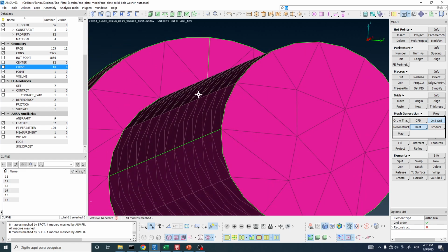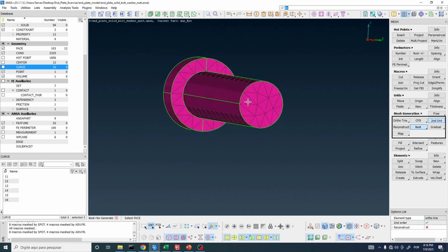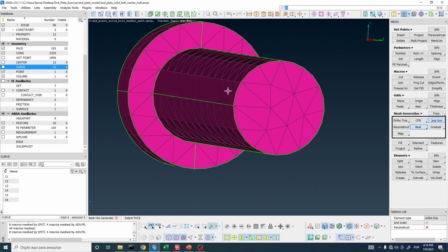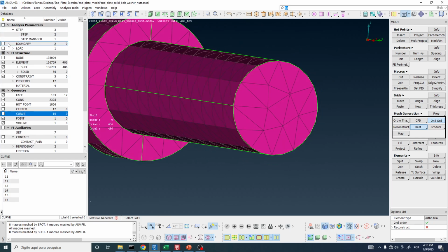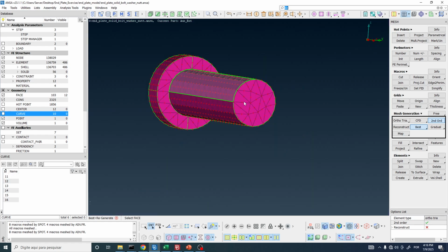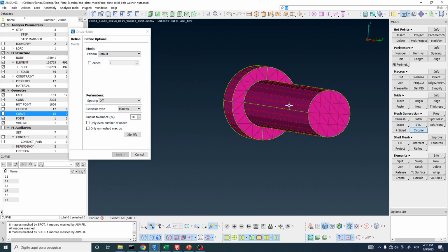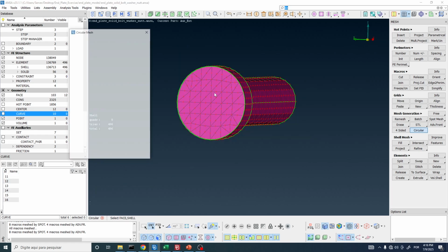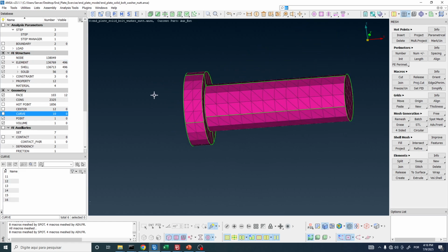And now if we zoom in, you see that we have the mid-side nodes and we have this curvature on the sides of the elements. So we are going to have the domain better represented because we have a circular boundary here. If we activate visualization of nodes, you see that we have the mid-side nodes. If you do this for the previous elements, you're going to see that we didn't have the mid-side nodes. Again, let's use the circular here on this face, middle mouse button again, and then here, middle mouse button, and again, deactivate visualization of nodes. And this mesh is looking pretty good.